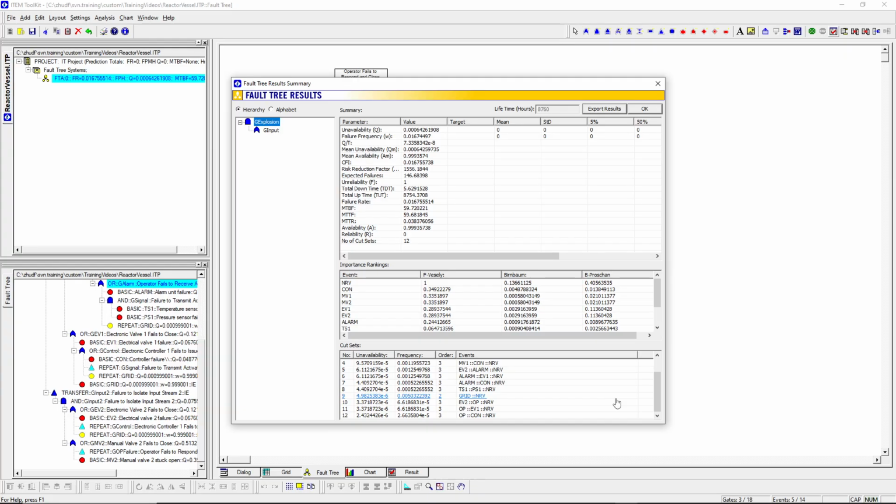By expanding the power grid's footprint to include the alarm system, a failure of the grid now simultaneously compromises both our automated electronic protection and our human protection layers at the exact same time. Because a single power failure knocks out both lines of defense, the Boolean calculation engine simplifies the pathways, collapsing what used to be a 3-event scenario down to a more vulnerable 2-event chain.